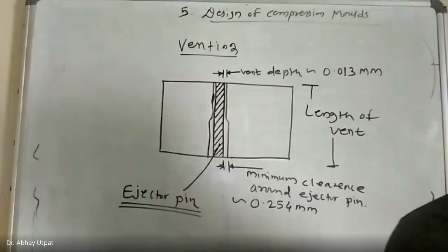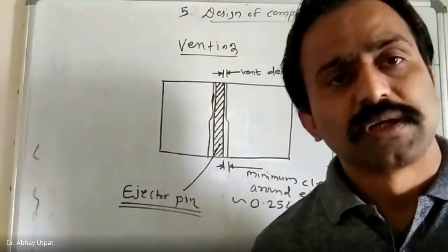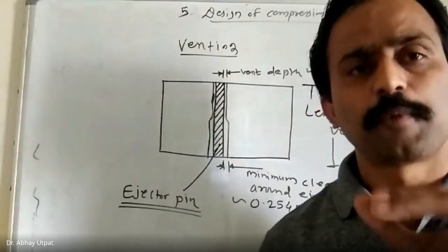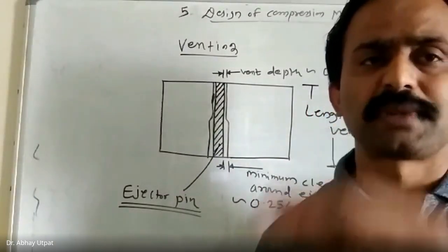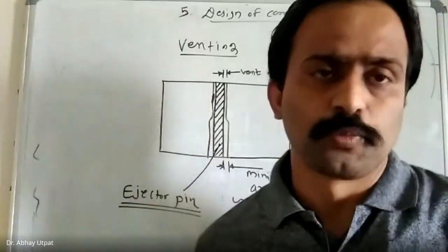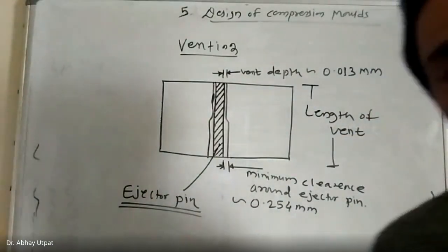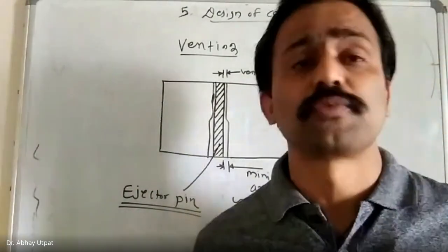Oil is half as efficient as steam. If you use oil or steam, you may achieve the mold heating temperature with a tolerance of 3 degrees. Means if you measure temperature at 2 random points, you will not find a difference of more than 3 degrees. Then you can say that you have achieved good and uniform heating of the mold.